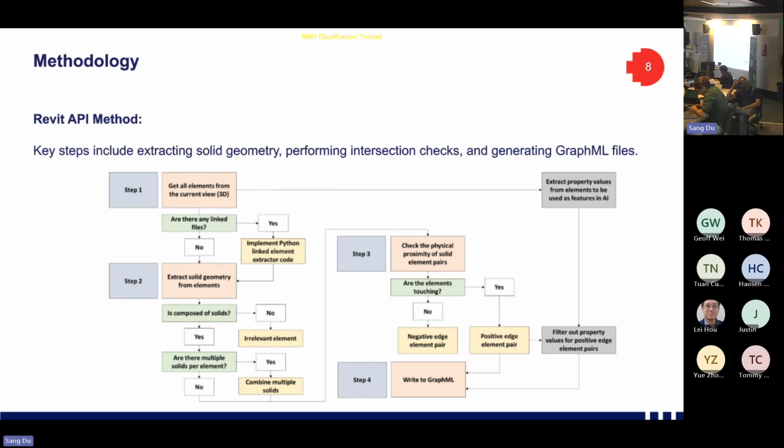and then we are writing this into Graph Markup Language files. The important thing is you can also extract additional information from the building information model which is relevant to facilities management scenarios. These can be simply areas, volumes, or other things like warranty information, manufacturer information, or whatever you want to add to the same GraphML file, and then later use this with your GNN analysis.